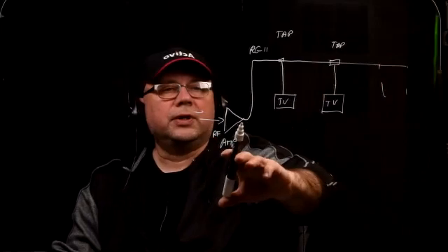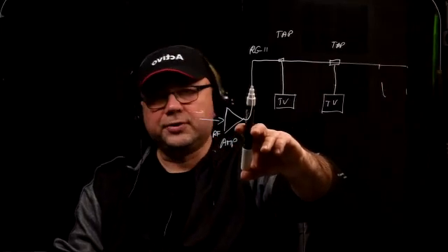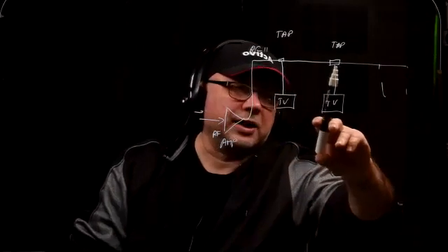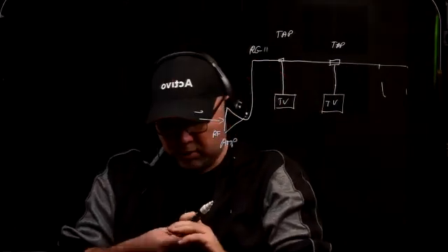Although RG11 has less loss than RG6, it's still going to have certain signal loss as you travel down the length. And remember when I said the higher frequencies deteriorate more than the lower frequencies? Still keep that in the back of your mind.